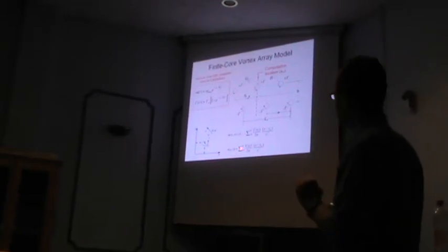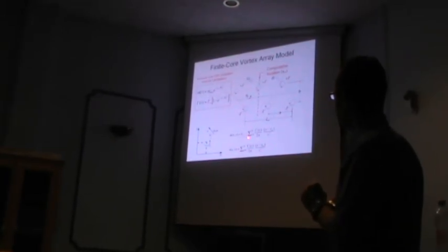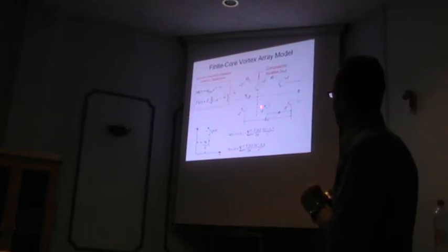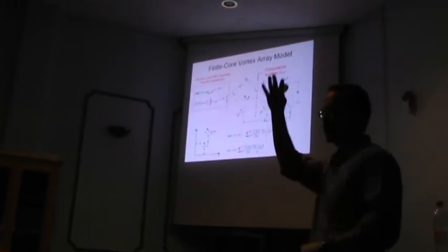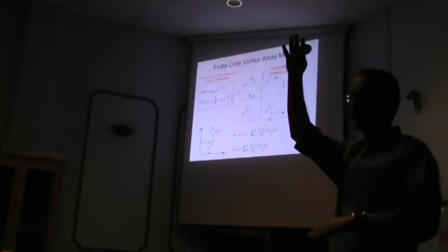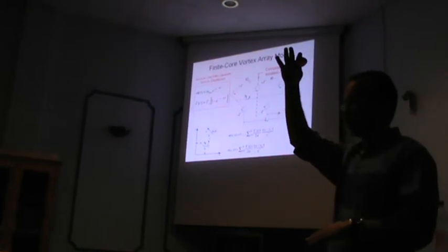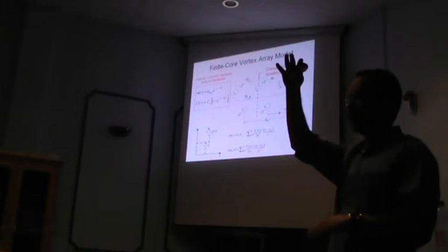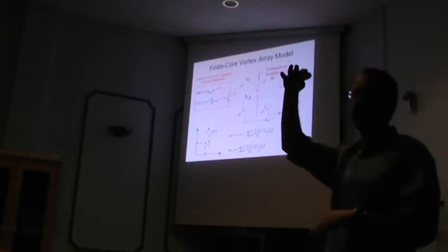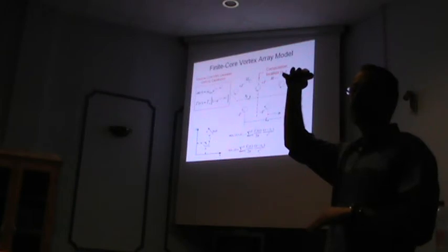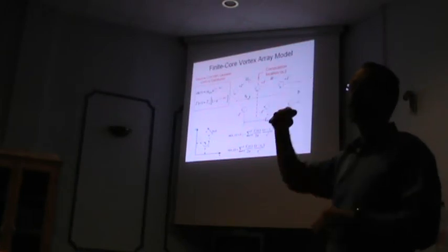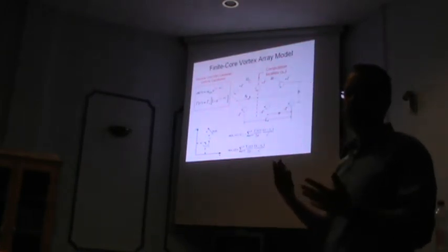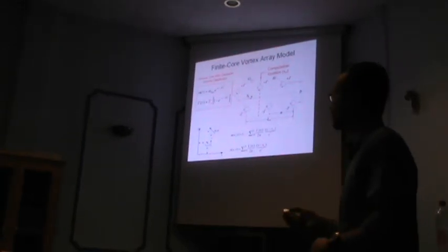However, in addition, we add on top of this a uniform flow u infinity because we need to meet the boundary condition that as you go far away, the velocity decreases to u infinity. And this is allowable because, as I said before, the Biot-Savart calculation gives you the velocity field within an arbitrary potential flow field that you actually pick to match the boundary.